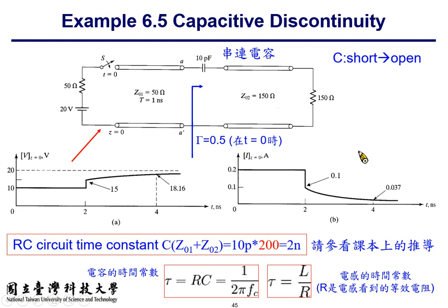Okay, so as you can see, the propagation delay for the first section is 1 nanosecond. How about the second section? Oh, well, we don't have to worry about the second section because the right-hand side is terminated with another 150 ohm, which will set up no reflection on the right-hand side. Okay, so we will only view the V plus signal.